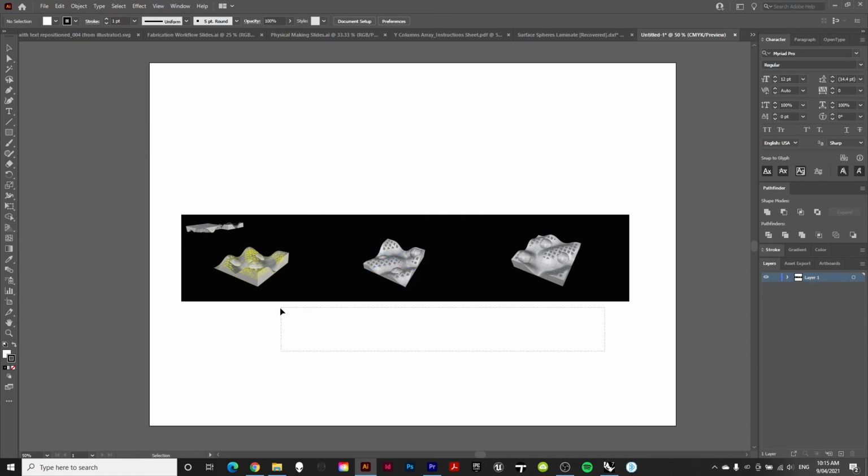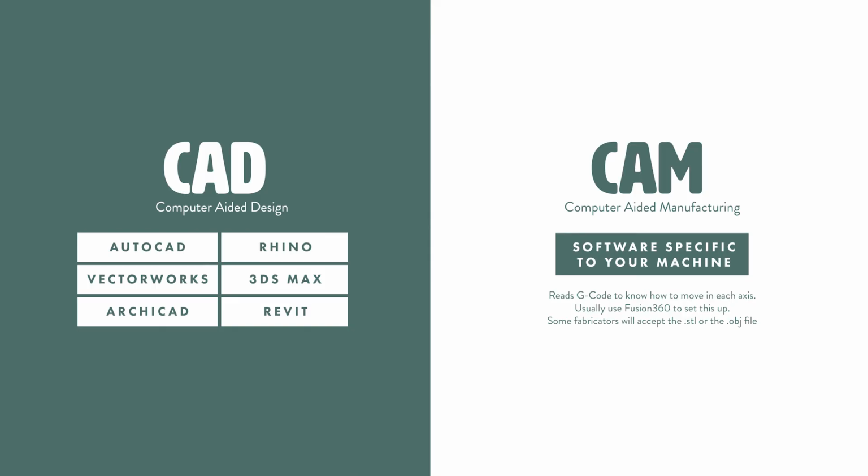And you also might include information like whether or not we're milling inside the line or we're cutting outside the line. So if we're milling down some shapes, we'd be inside, or if we're cutting out some objects, we'd be outside. So that is the process for the CAM end of our workflow, and hopefully you can see here how we would take our drawing or our model from Rhino, get it ready and export it out so that it can be taken through to the CNC machine.